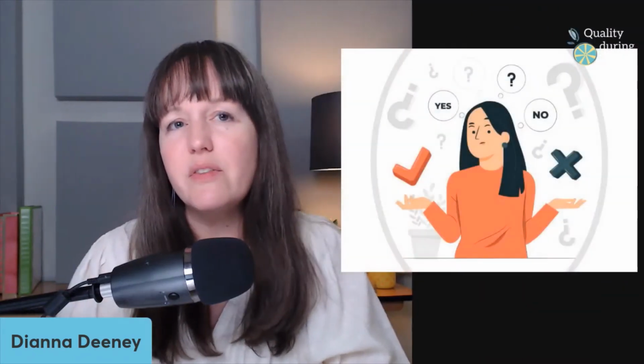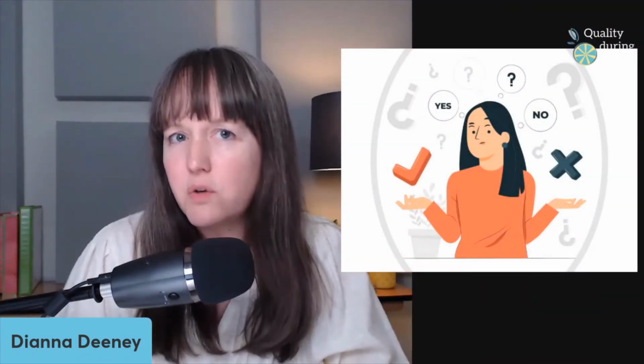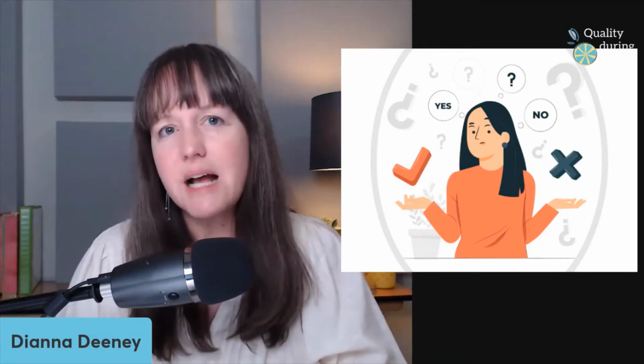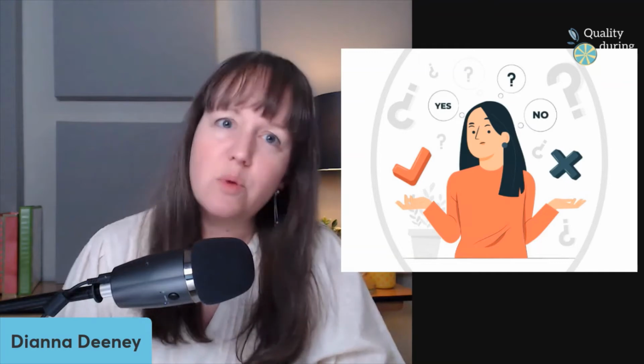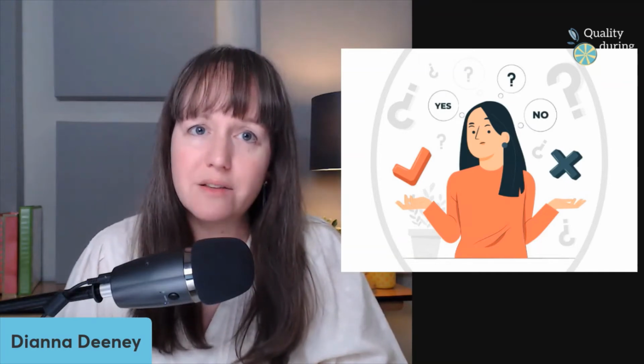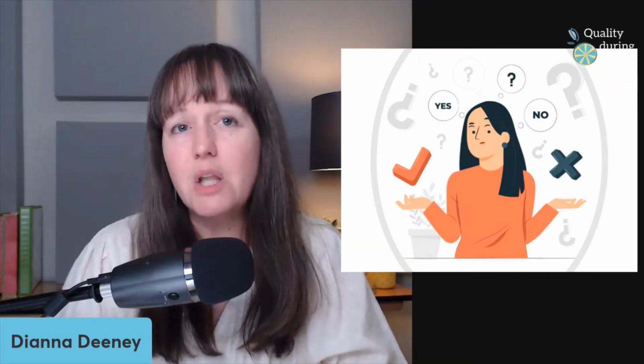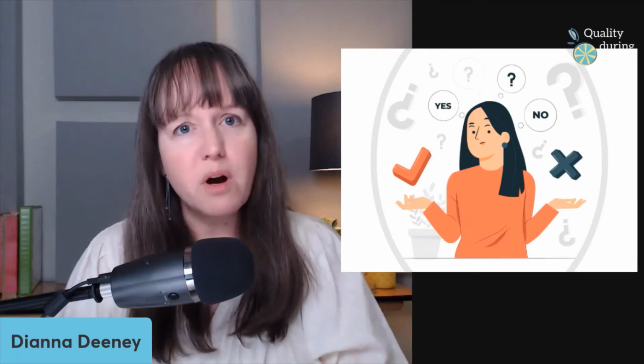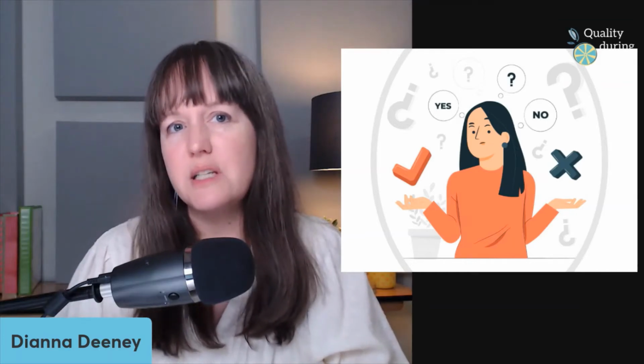If we have a potential usability failure, where there's an issue with how our user interacts with our product, we want to think about what user process controls we have in place to prevent the failure. Like the user can only orient the part this one way because of the design. And we think about how our user will detect the failure, like an alarm that's designed to go off if a condition is met, or the part is labeled for the correct orientation.